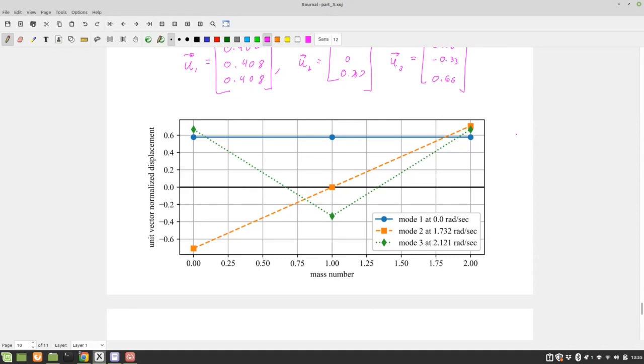How that manifests itself in flight is a totally different discussion, and there's really not any information in a common fixed mode like that. Once you start dealing with that stuff, it gets very specialized. This is something they considered a lot in the design of the space station. If you were to excite that plane at a random frequency, would you see that first mode, or would you only see the second two modes? If you excite it while you're flying, maybe.